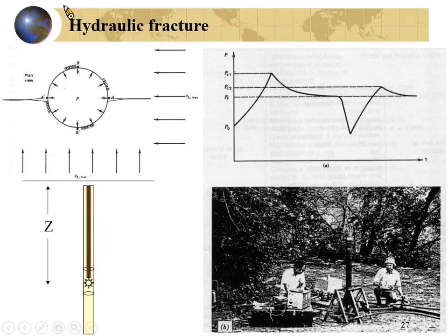Sigma r and sigma theta, right? Sigma r will increase with the distance to the tunnel center, but sigma theta will reduce with the distance to the tunnel center. So, when the pressure overcomes the sigma theta around the tunnel wall, the resistance will decrease with increasing distance.